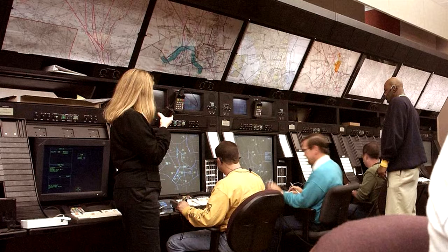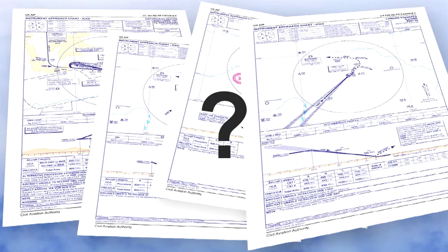When this occurs, aircraft shall be instructed to follow and maintain separation from preceding aircraft. Normally, the approach controller will specify the instrument approach procedure, IAP, to be used. However, if the pilot requests a different approach, this may be granted.